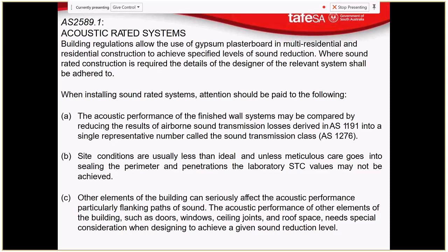So there is a little bit of variance, and that's what this second point refers to. Site conditions are usually less than ideal, and less meticulous care goes into sealing the perimeter and penetrations. Laboratory STC sound transmission class values may not be achieved, but there is some accommodation for that in Australian standards.